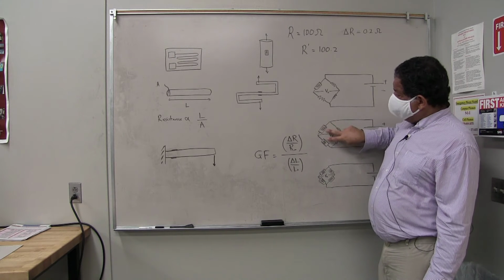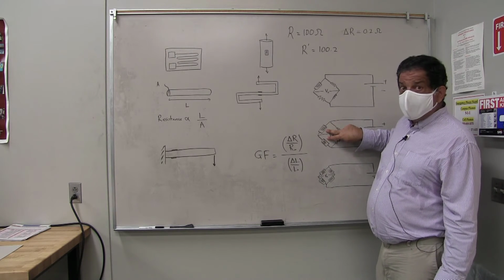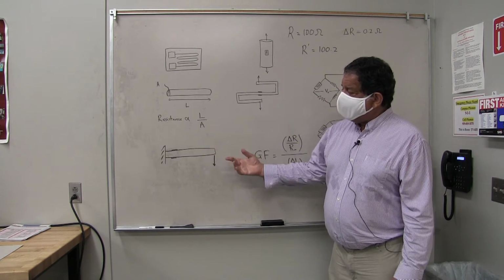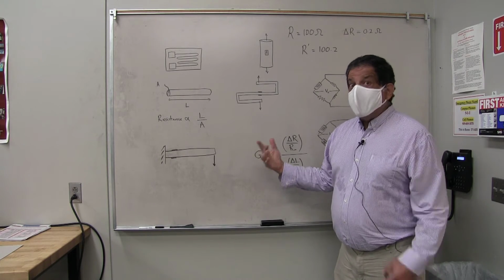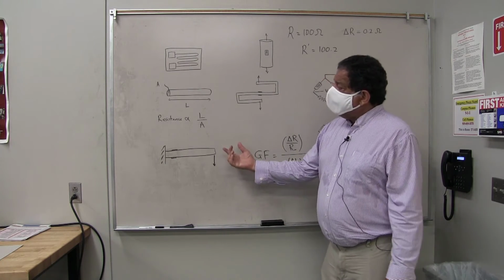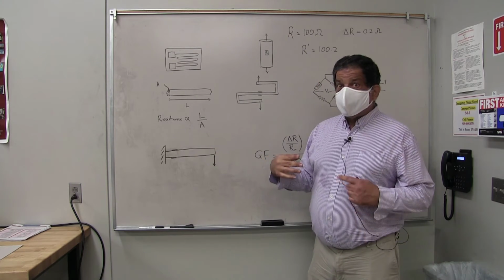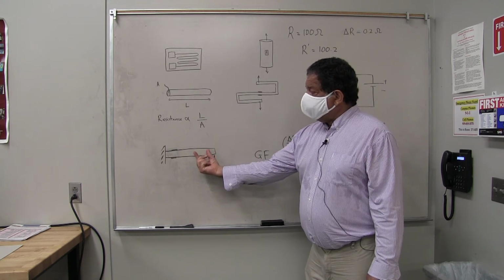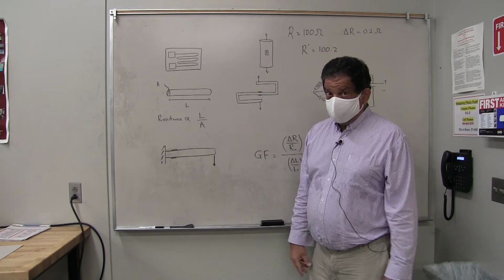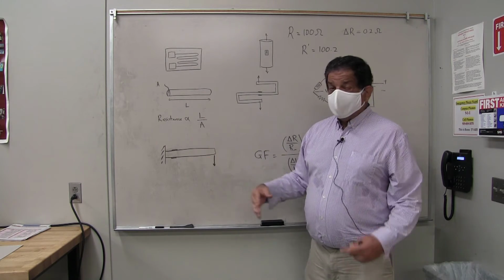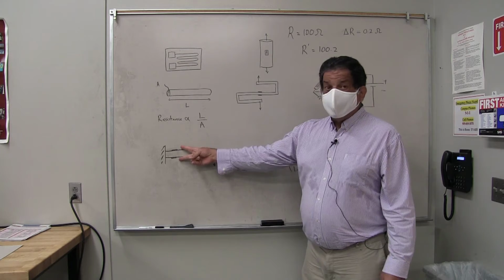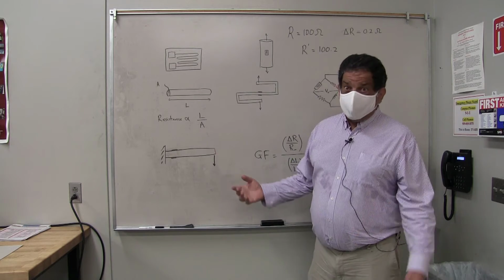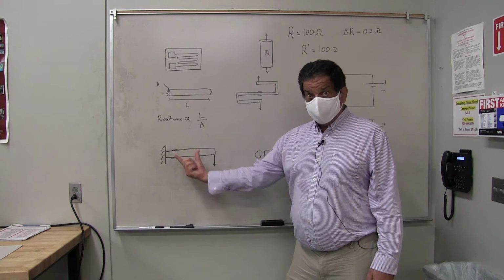There's another advantage of this half-bridge setup though, which is what I'm really trying to do in this experiment with the beam and bending, which is to pick up the bending strains, right? But this object might have things on it other than bending strains. Like for example, let's suppose that it's also undergoing tension and compression. Or let's suppose that I glue these things on when the lab is 70 degrees Fahrenheit, and then I do my experiment when the lab is 80 degrees Fahrenheit, and then I might have thermal expansion, right?